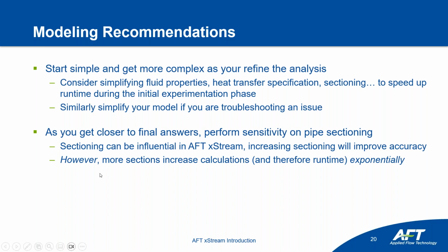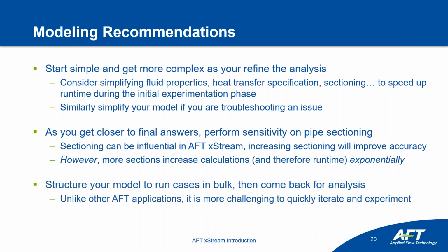However, as we mentioned, the more sections you add, the more calculations you're going to have. So how many points and how many time steps are you calculating? And therefore the runtime to perform all those calculations increases exponentially. If you double your number of sections, it doesn't double your runtime, it will actually quadruple it. And again, lean into how you're building your model, so that if it does take that long, you can run all of your cases, come back, and do your analysis. Maybe you run your systems overnight, things like that.